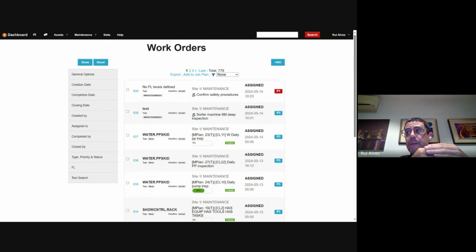So you can manage perhaps a little bit of a decrease in performance of the machine. So you buy some time, for example, to get spare parts to allow you to do jobs during that planned shutdown. I recommend that you pre-organize the works that you plan to do during that planned shutdown in some way, and the best way to do it is adding tags.